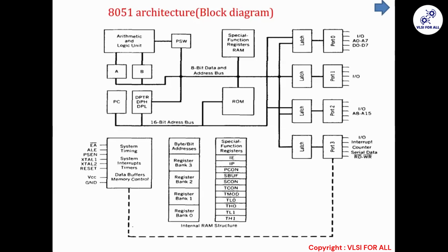This much internal RAM or ROM is not sufficient for me. RAM is not sufficient, so I need some external memory to be connected. With the help of this address, I am addressing a location of external memory. Some data is there, fetch it.